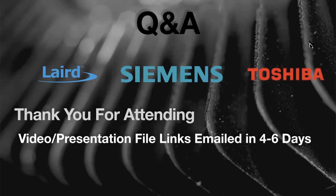So the thermal conductivity in the XY on a synthetic graphite pushes 1,000, which is really, really high. And the Z conductivity is in the 10 range. So there's a big difference between the Z plane and the XY plane. Graphite is a really good heat spreader. And so what we're trying to do in large gap applications is move the heat around the outside using that high thermal conductivity in the XY.